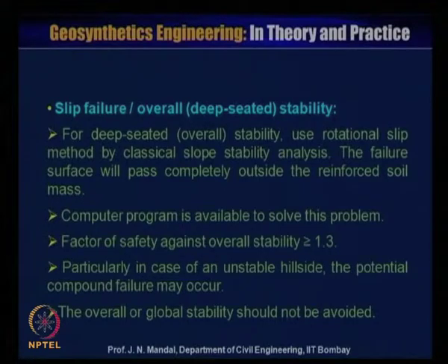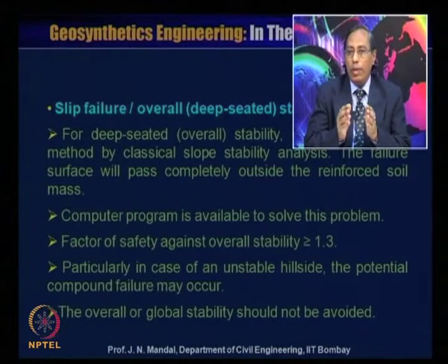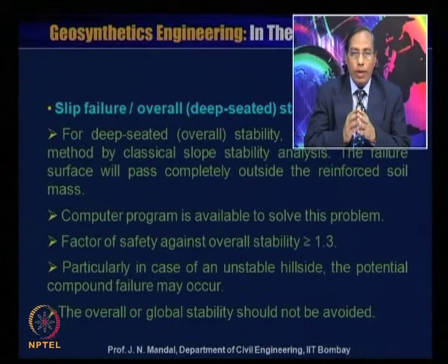Now next is the slip failure, or overall or deep seated stability, or global stability. For deep seated or overall stability, use the rotational slip method by classical slope stability analysis. The failure surface will pass completely outside the reinforced soil mass. Computer programs are available to solve the problem.